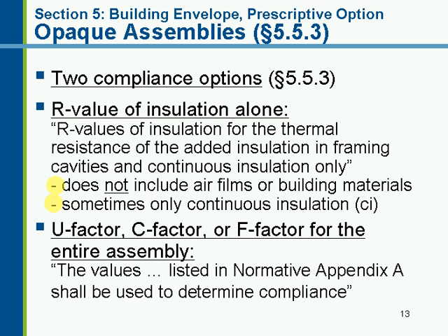So when you're thinking about this, it's meant to be really easy for you as a designer or contractor, easy for the building plans reviewer, easy for the building inspector. So you're looking for the bat insulation, whatever the R value is on the bat, that's what we're talking about in the prescriptive tables here. Or if you have rigid insulation, it's whatever the R value that's on the foam here.